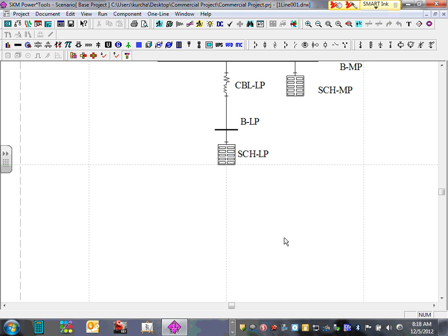The lighting control panel, Aaron, because it's only 20 amps, we feed it as a load. We don't even show it. Guys, security panel, lighting panel, fire alarm panel, phone data hubs, all these are 20 amp circuits. They are branch circuits. They are not feeders. So when we do the analysis, they are so-called peanuts. They don't count.